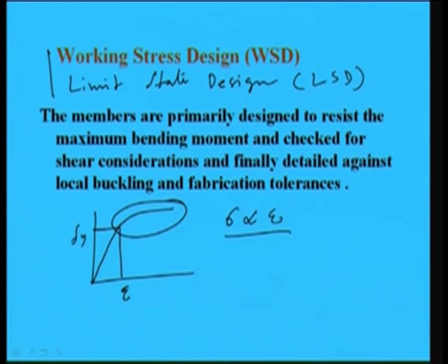But in our country, in India, so far we have not introduced the limit state method of design in case of steel. In case of concrete design, we are well conversant with the limit state method of design, but in case of steel design, we are not using the limit state method of design. So far we are using the working stress method of design.